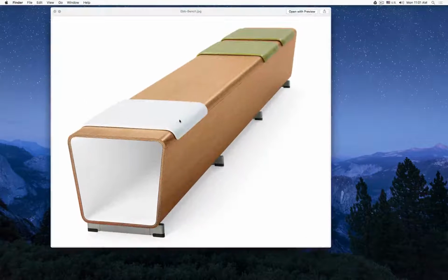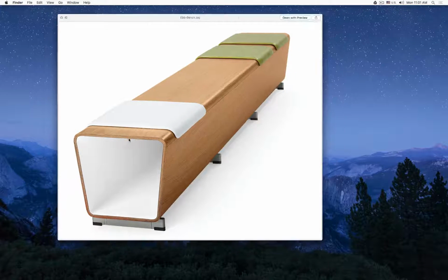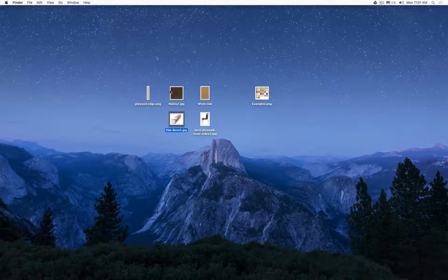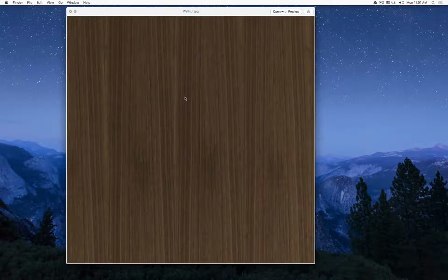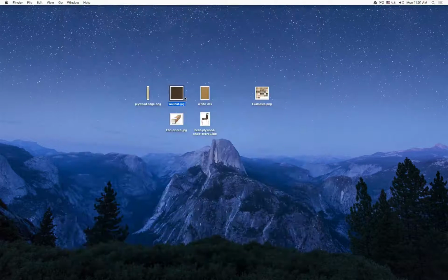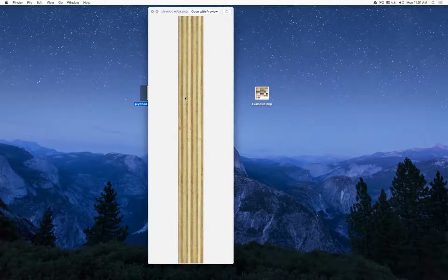So when we work with bent plywood, just as a refresher, we work with a kind of composite material, and that has visually two properties. We have an inside and outside top veneer, and we also have all the layers. So basically we have to deal with two different textures. So for example, you can select a top veneer material and then a side veneer material.